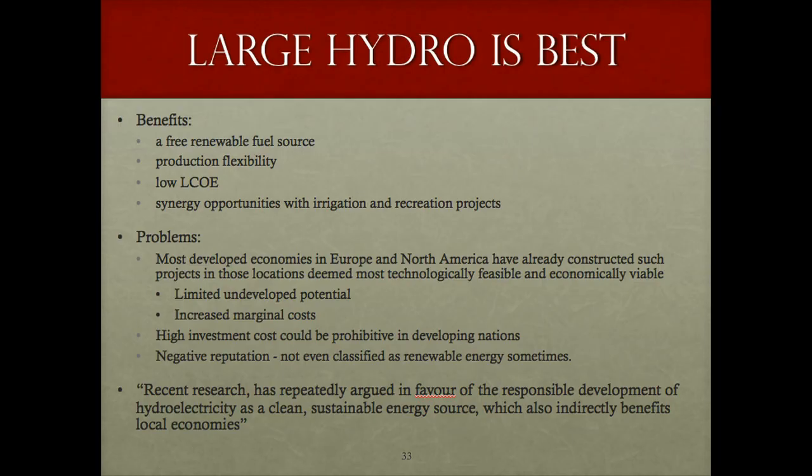Large hydro is on top, mainly because it is a free renewable fuel source. It's flexible, it has a low LCOE, and there are synergy opportunities with irrigation and recreation projects. However, it may be surprising that hydro is on top from the U.S. perspective, because most developed economies in Europe and North America have already constructed hydro projects in the locations deemed most technologically feasible and economically viable. Therefore, there is limited undeveloped potential in these regions and increased marginal costs.